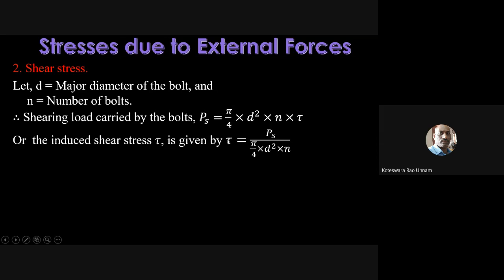So using these formulas you can calculate the shear stress. If you want to compute the shear stress, you can use this, or if you want to calculate the shear loading capacity, you can use this formula. Both the formulas are the same, we are only arranging them in different ways. That is the only difference here. Then you have a combination of both tensile stress as well as shear stress. If the bolt is subjected to both tensile stress and shear stress, then now we can design the bolt.